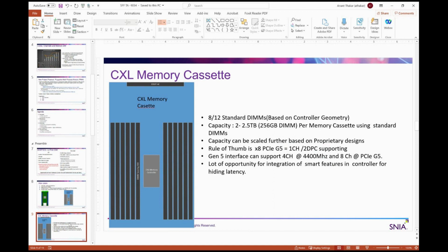So you could scale that. There will always be a delta between the memory speed of the locally attached CPU versus on the CXL. That's going to happen because ultimately the bandwidth is x32 Gen 6, correct? That is what your input bandwidth is going to look like. So essentially you're looking at 32 lanes PCIe Gen 6.